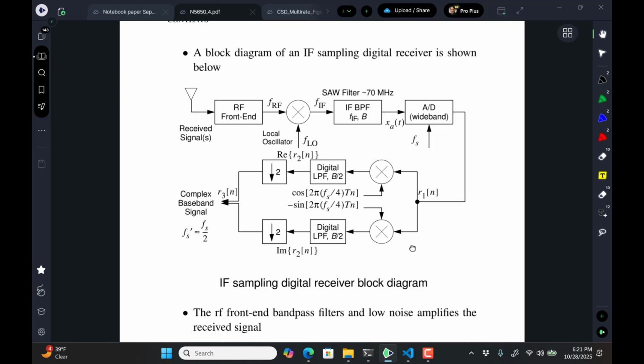So once we have the 70 megahertz IF where our signal gets shifted to, then we have to decide how we can recover our channel signal of interest off of that. So we go with a wideband A to D that can sample directly at 70 megasamples per second or higher, and then we undersample the signal. Because of that narrow bandpass filter, like the example I showed you in the animation one day, it's going to capture just that narrow band, and as it undersamples it, it'll move it down in frequency, while filtering out all the adjacent channels, like all the other cell phone channels.